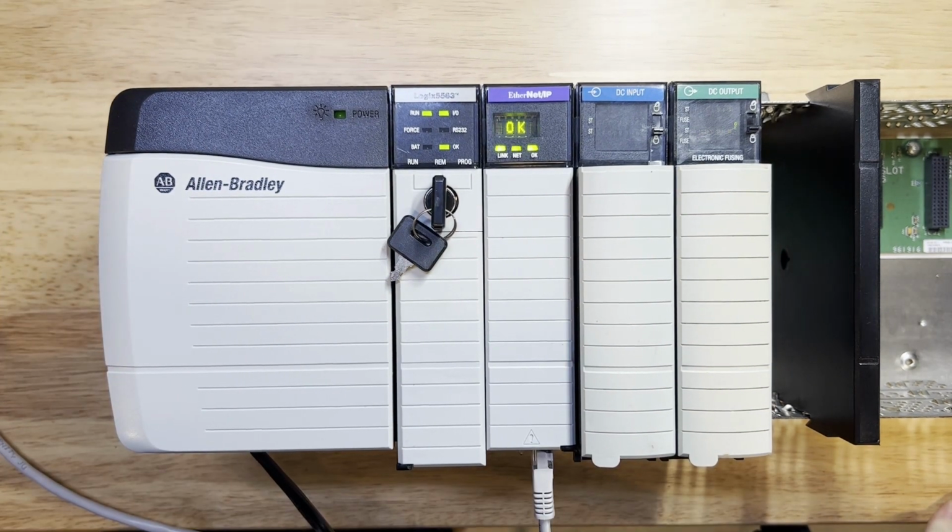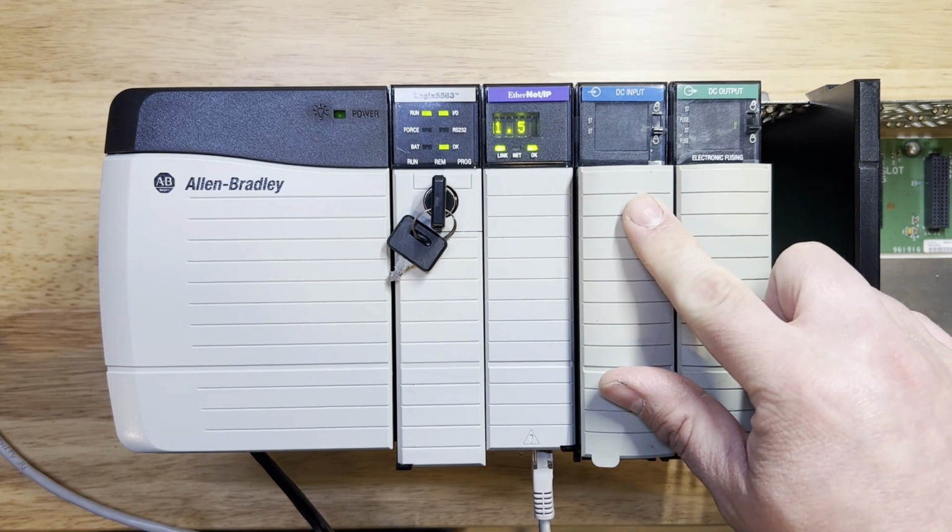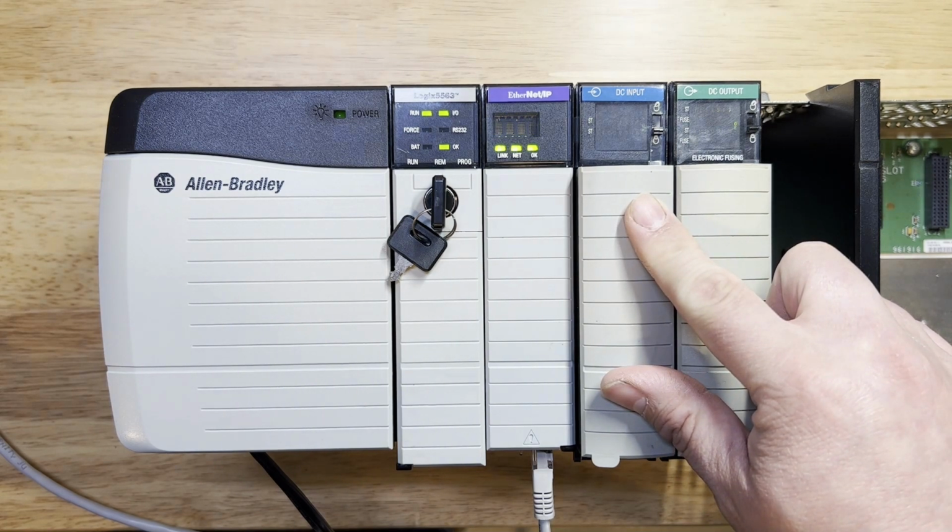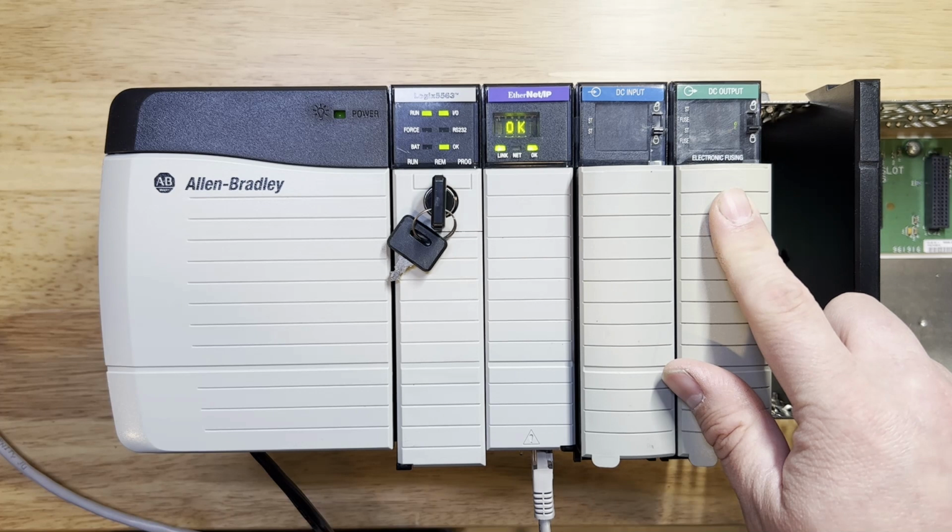When diagnosing a problem with the program, the input lights will tell you which inputs are high. The output lights will actually tell you which outputs the program is driving high. If for some reason there is an output that is on, but you're not getting an active solenoid, relay, etc., then there may be an issue with the device connection.